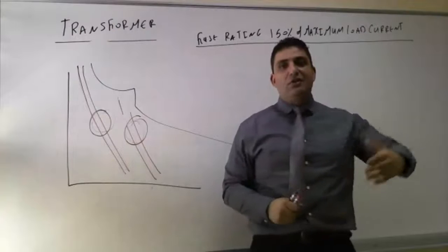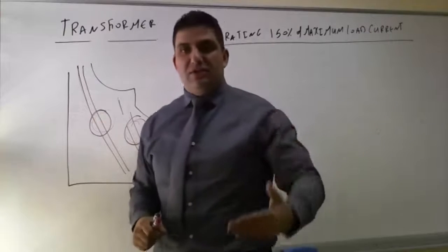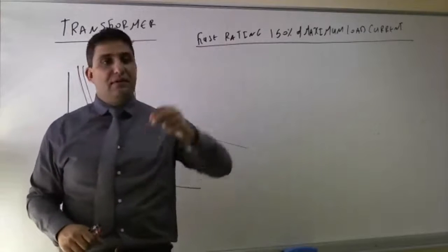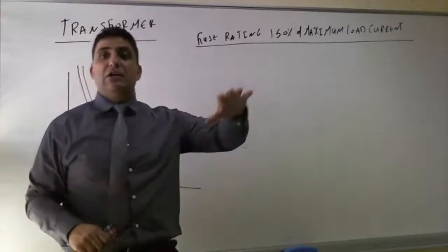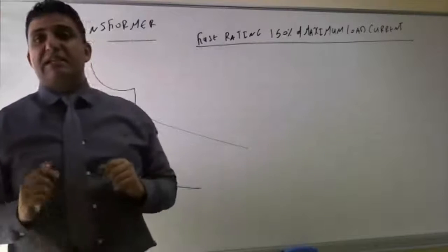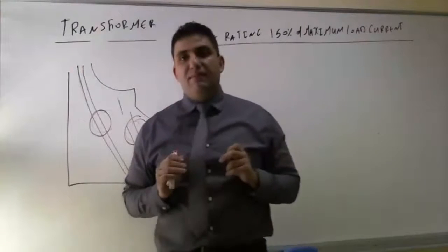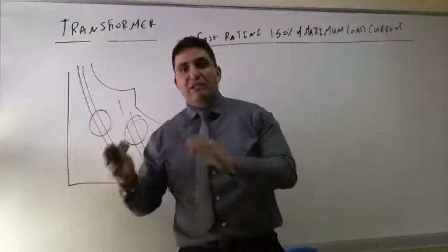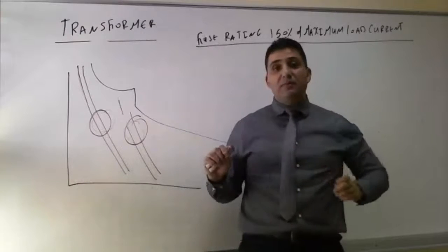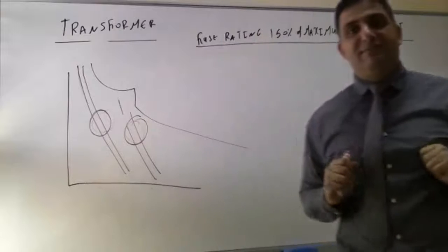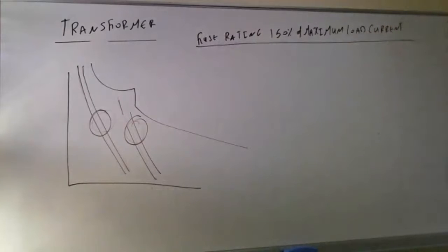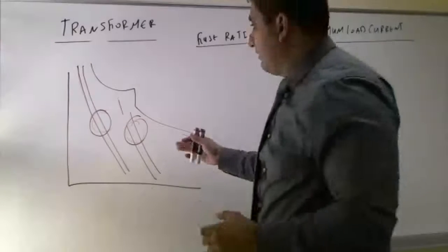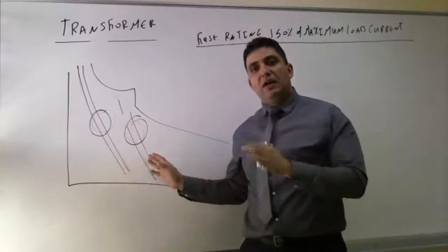So I can ask you to determine the type of protection required for this transformer if it is located in a standard, normal area and its capacity is 7,000 kVA. You should be able to tell me the typical protection required for this transformer is the induction disc over current relay. Like I said before, you already covered the time delay, instantaneous and time delay over current in the previous chapters. We are not going to cover it.